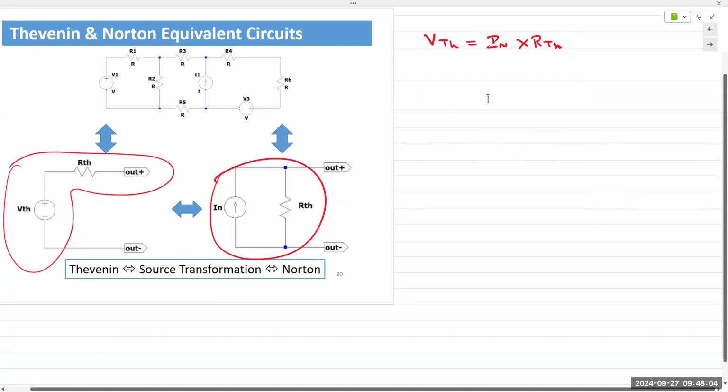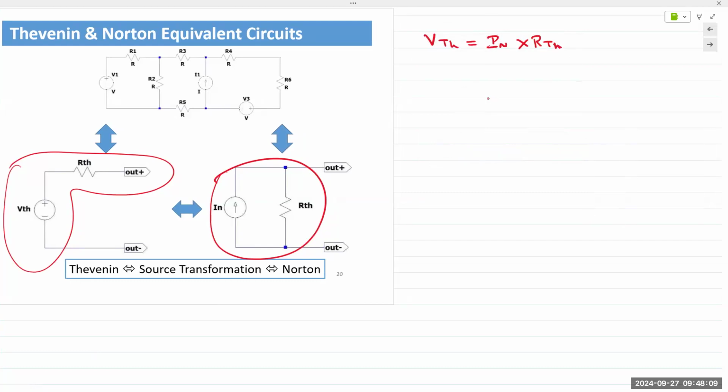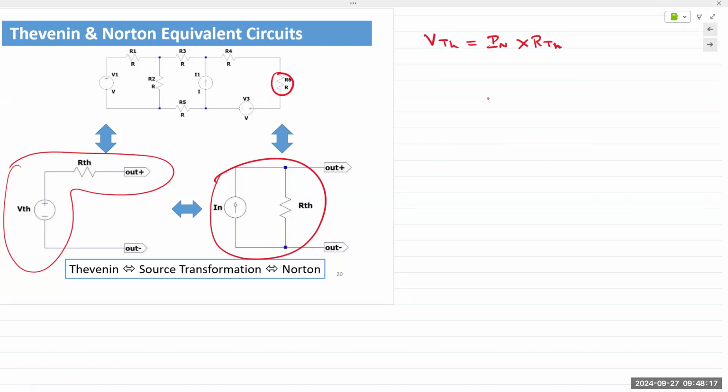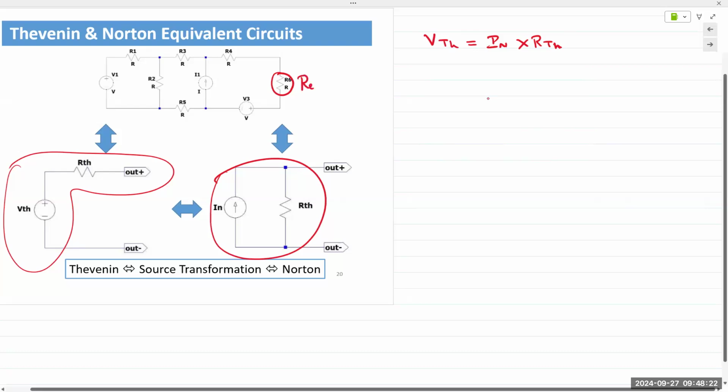In this example that I use when I teach circuit analysis, I'm stating that we wish to find a value for R6. So if you're trying to analyze the circuit as seen by R6, you have to remove R6 from your analysis, and you're left with open terminals. I simply call them V out plus and V out minus. It's just the notation I use. You analyze the circuit between V out plus and V out minus.